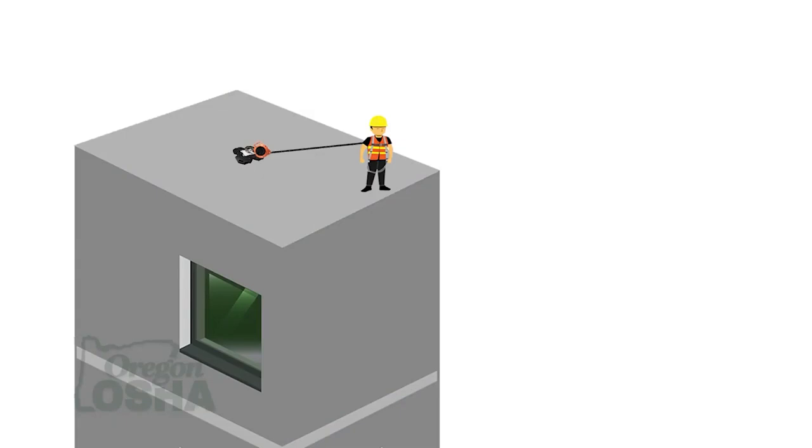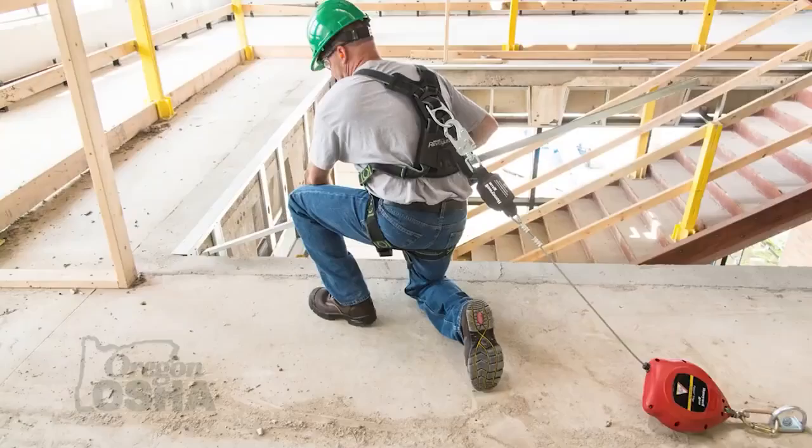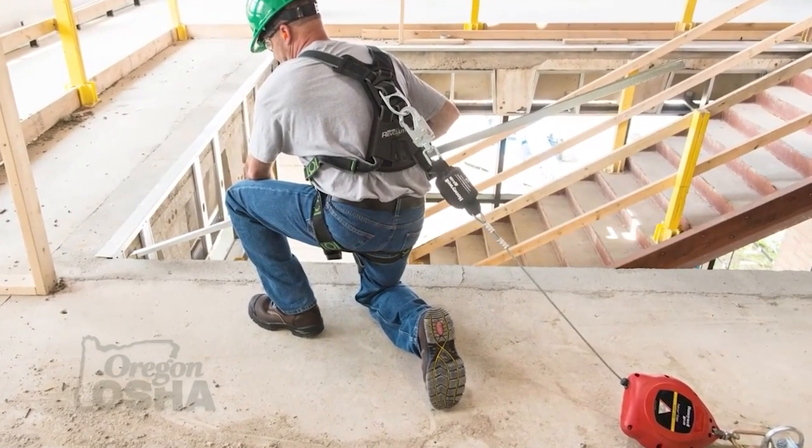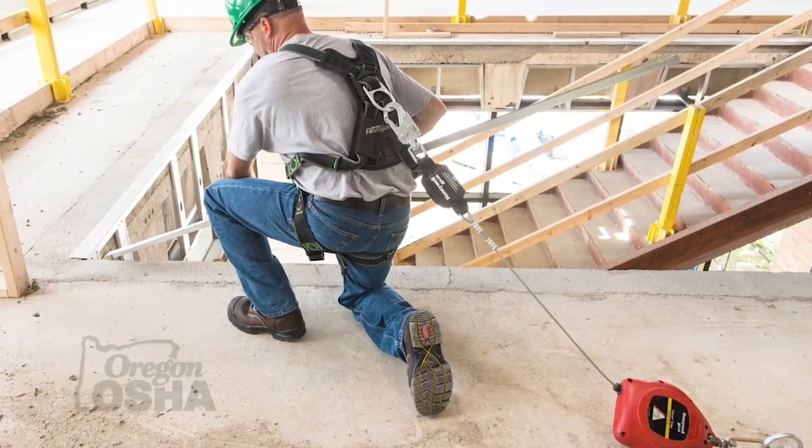When we have the arresting device with the worker and they take a fall over that edge, it's going to function. It's going to reduce the forces that are put both onto the fallen worker and onto that edge where the lifeline is contacting that edge. It has the ability to reduce how much swinging and bouncing that lifeline has on that edge at the same time.